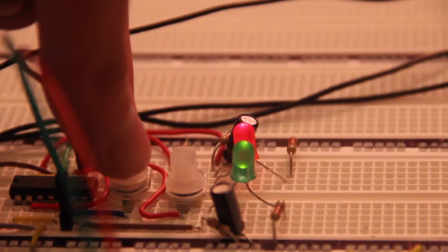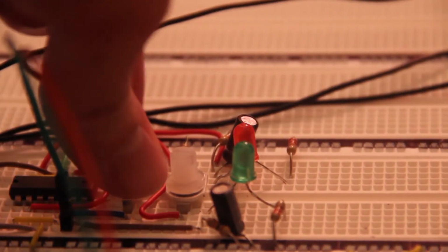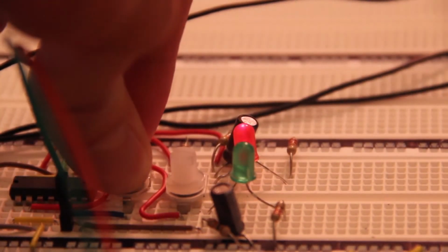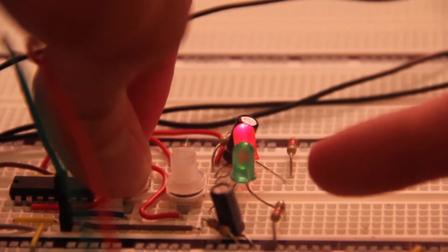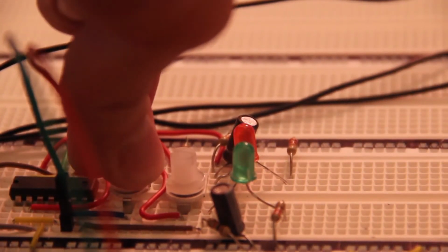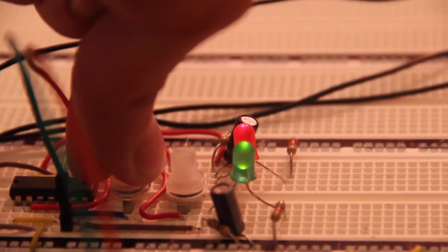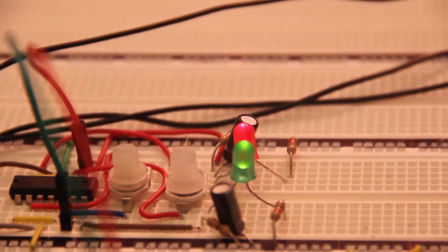And don't forget to check that your pots work. You're going to want to tune these LEDs so that they're blinking at the appropriate brightness based on the amount of music. So if I turn this down, you can see that the green LED blinks less and less. So we want to tune it to an appropriate value where we're getting a good amount of brightness where you'd expect the peaks to be. And once at that value, that's perfect, and we can feed into the Arduino, do some awesome programming, and make it control the whole LED strip, and it's going to be really great.